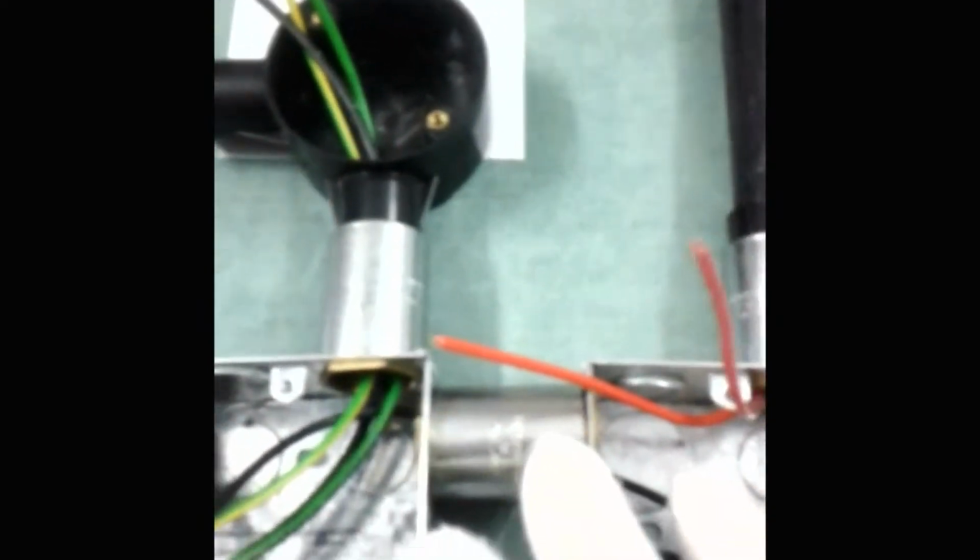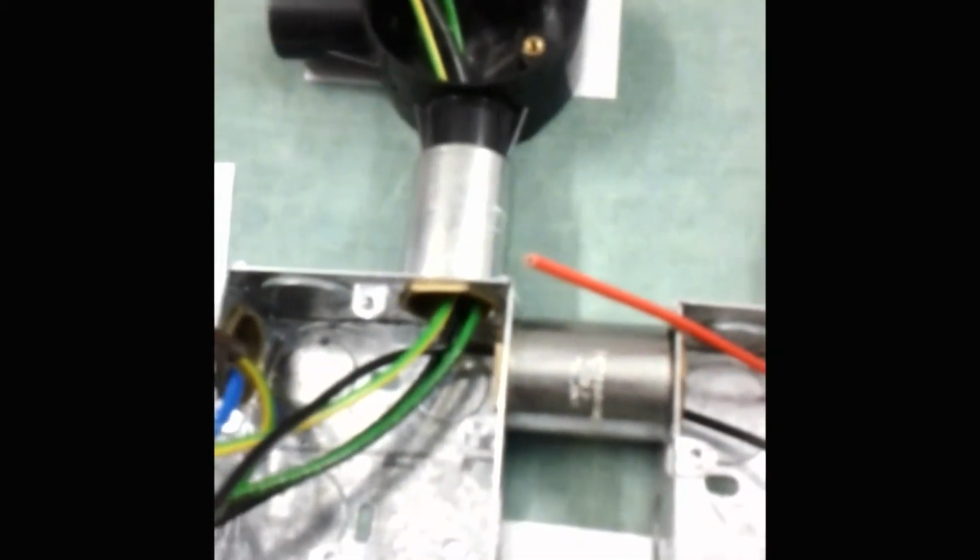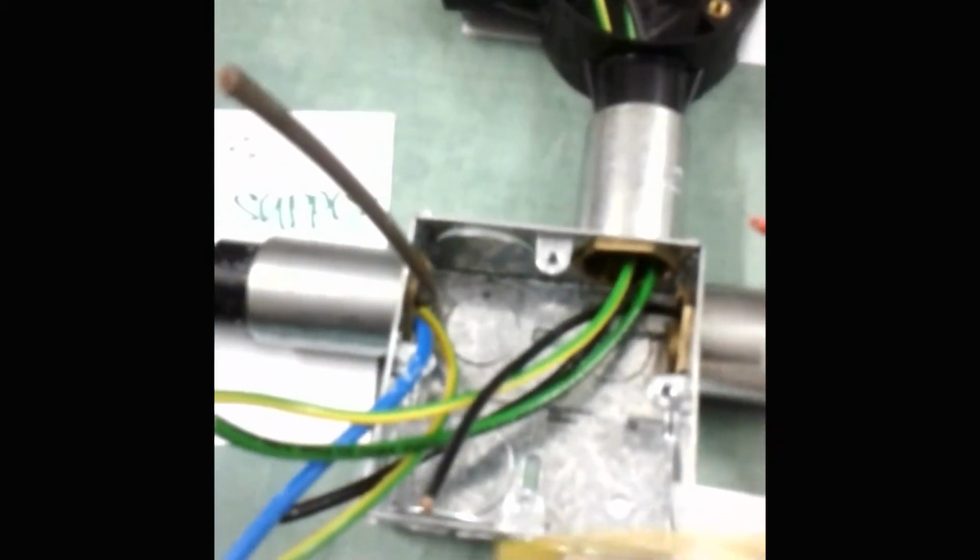Okay, and we have another wire here which is also our earthing wire, and from the roof floor ceiling down light we will run another neutral line going down to the first floor switch, because our power supply is coming from the first floor, so we are going to run all our neutral line to the first floor.